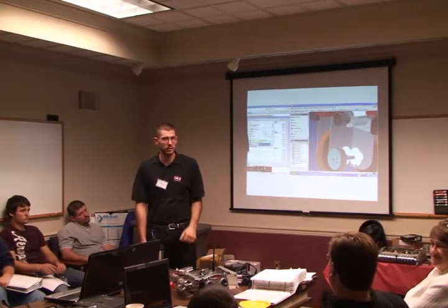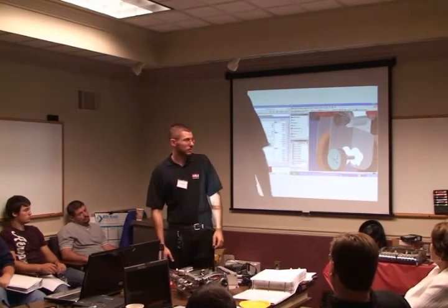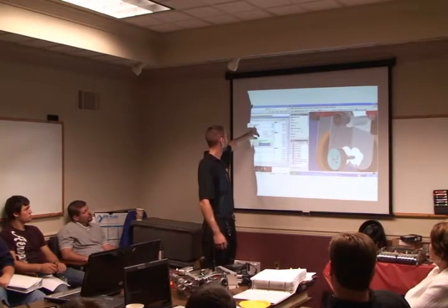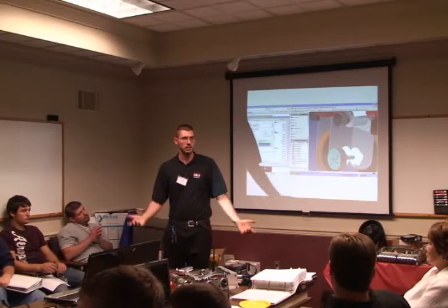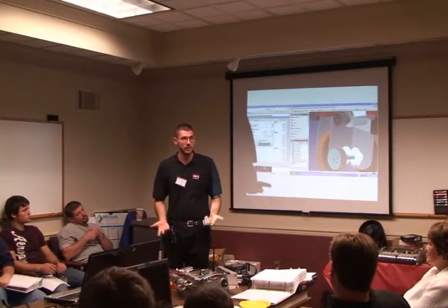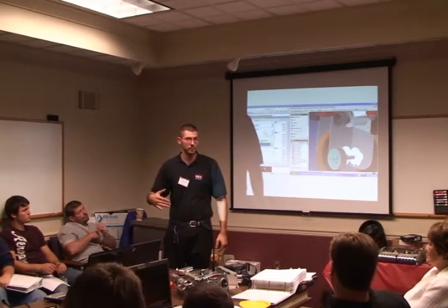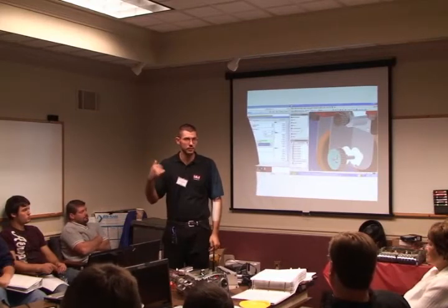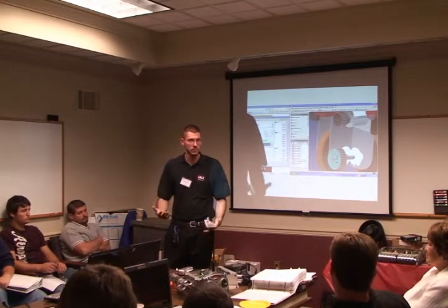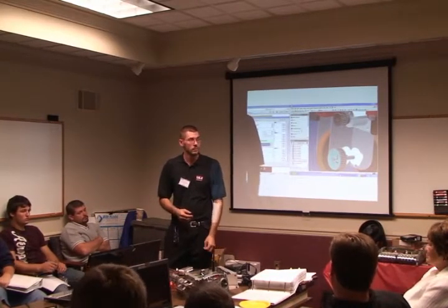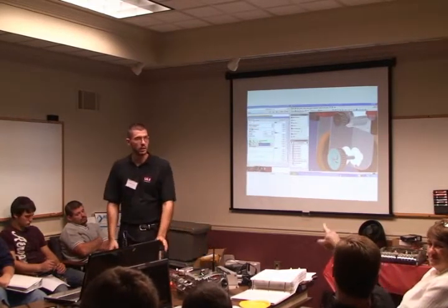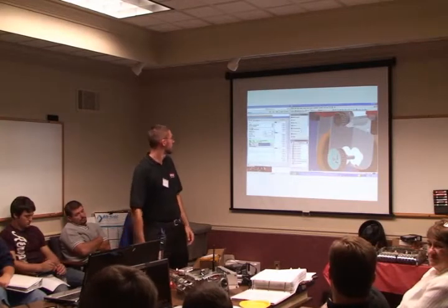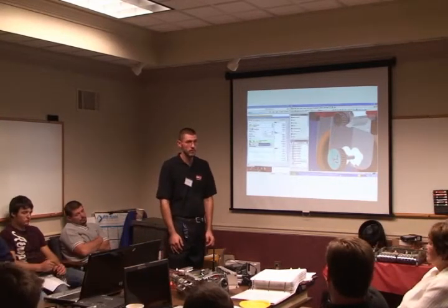Does it do pitch and everything too? Yes. You can pick different belts over here, so it'll actually tell you your pitch here. You can say you want to use a double-sided MXL belt, and it automatically pulls up what's industry standard, whether it's a 100-tooth belt or a 90-tooth belt. That's in Inventor. I know SolidWorks does it also, but I'm not sure if it tells you the pitch of the teeth and stuff like that.